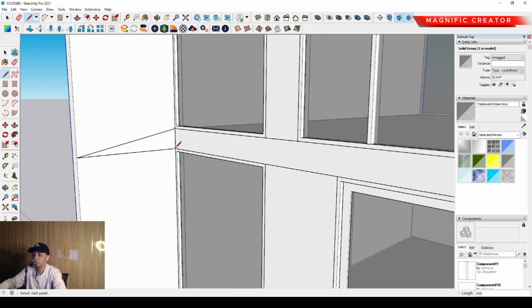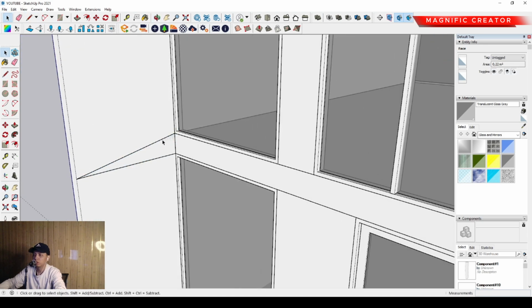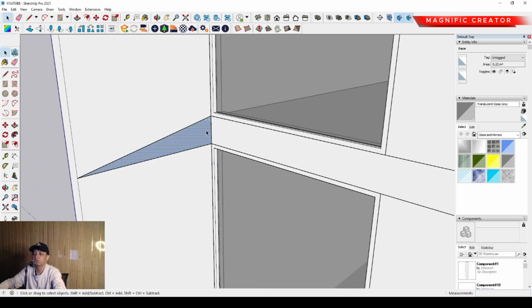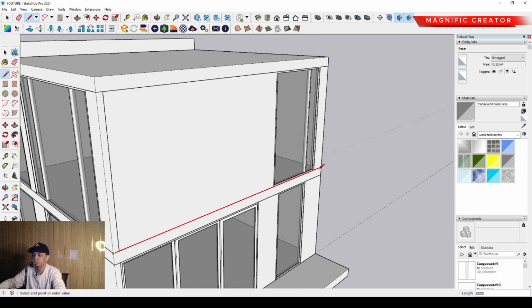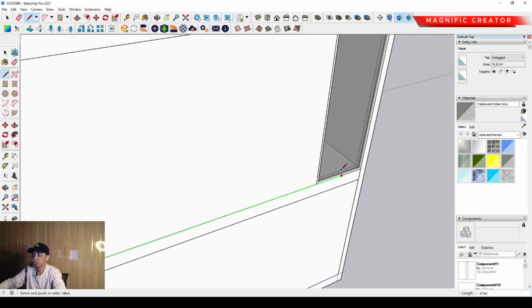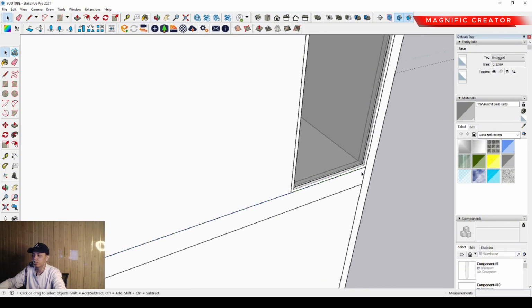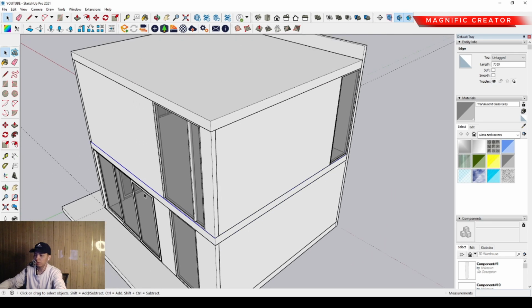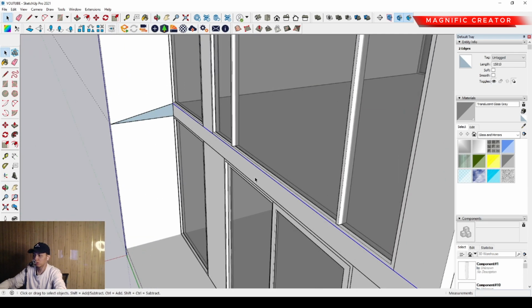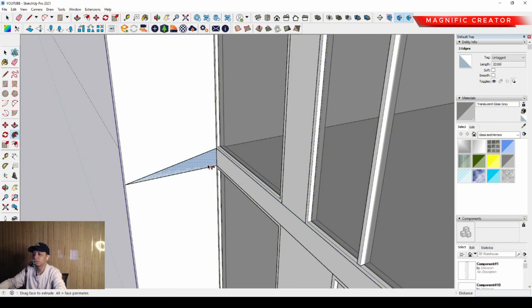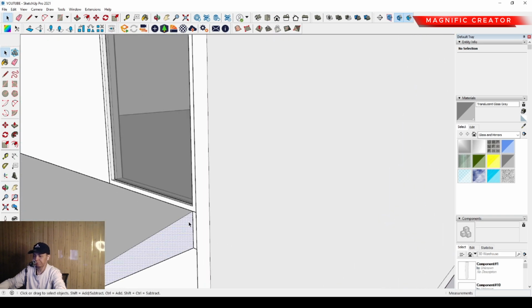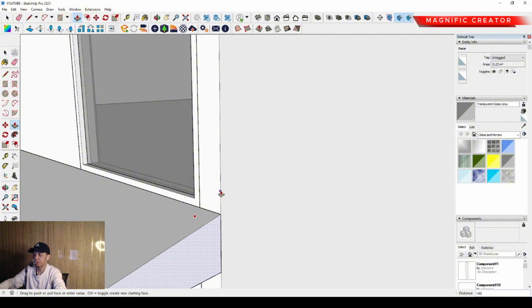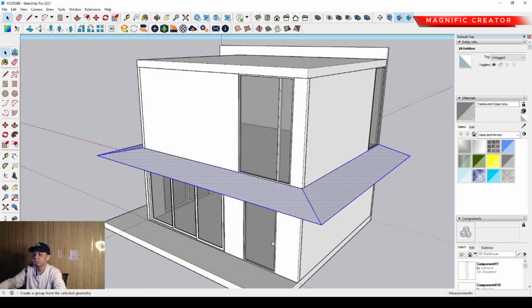But now we have to make the small canopy roof element. Maybe we can use the rectangle tool to draw the rectangle profile over there for this wall. Then we can make the Follow Me path with the line. Just follow this video. We can select this triple line, and then select the Follow Me tool, so it will be automatically arranged. Okay, something like this. Then we can just make it a group anyway.